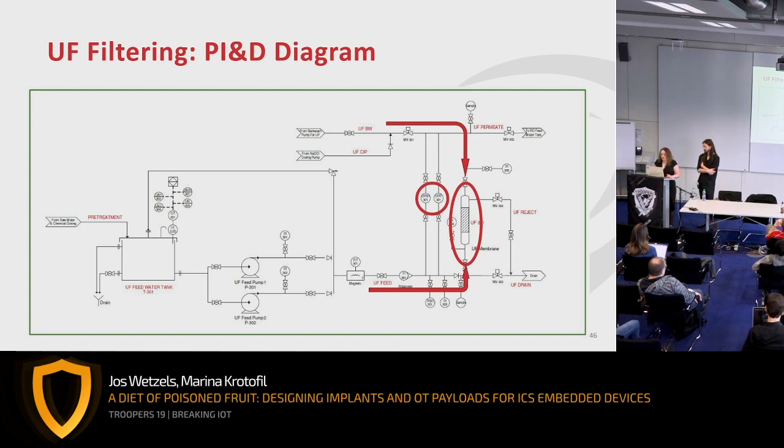And from the controller, we are able to figure out that the second pipe is coming from another stage. From the bottom, you have a normal water flow, which will be clean. And from the top, that comes from another stage, there is a process called backwash. Backwash is cleaning the filter from the particles which are collected. The idea is, what if we put two flows through this filter and raise the pressure? Because we know that pressure is very damaging for the membrane of the filter.